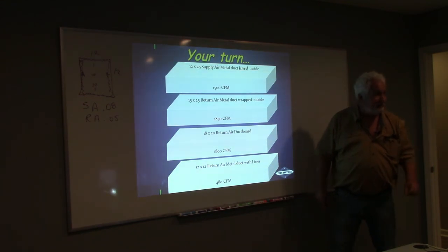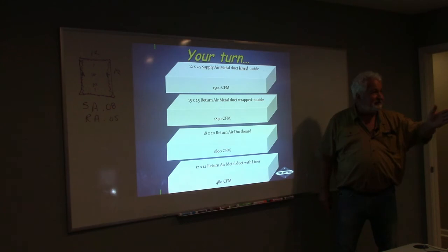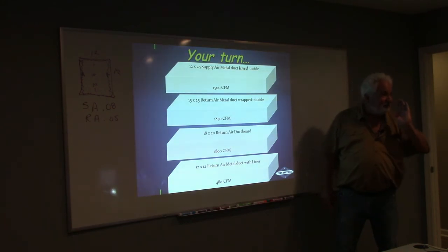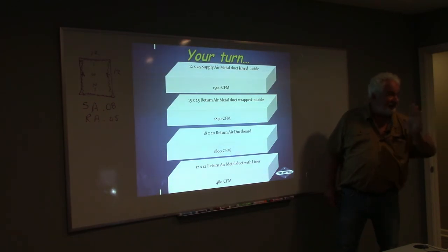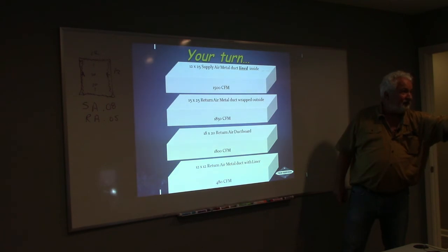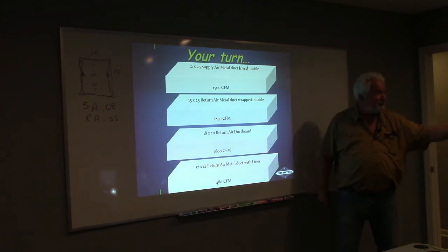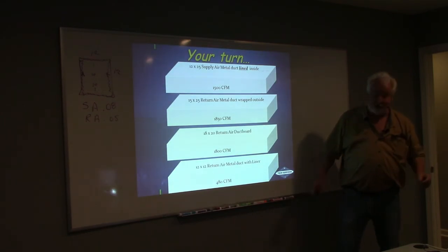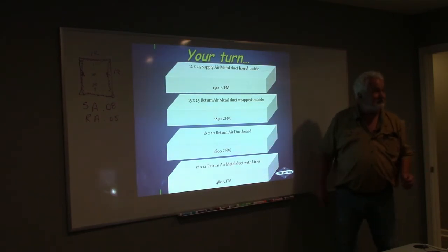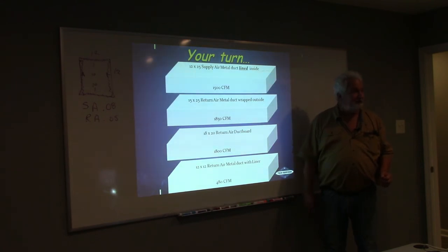Yes, it is, because for one thing, it's lined. It's glass all the way through. Your free area is the same, but the friction rate on that glass liner versus running down that lined metal duct on the inside. Isn't that crazy? So when people start saying, oh, I hate duct board, I hate duct board, I thought those two would have been pretty close. I thought it would have been a lot closer.